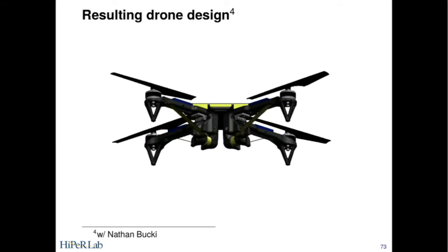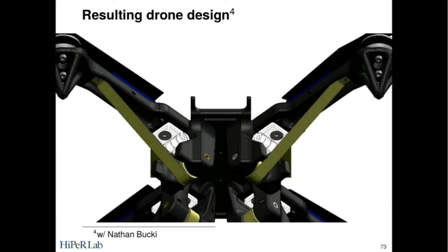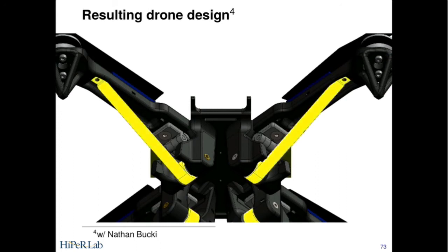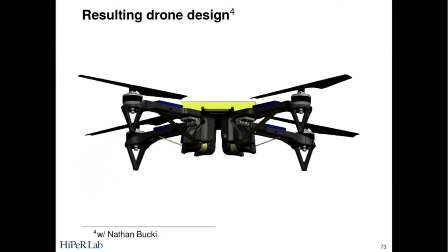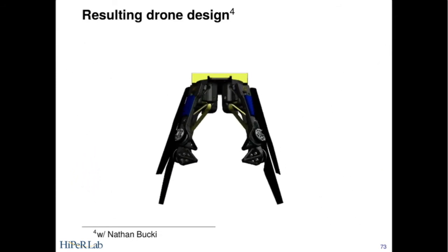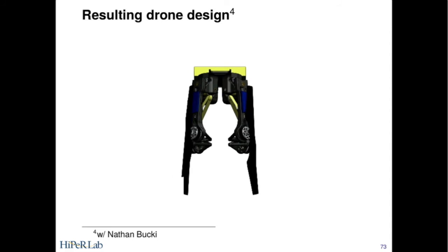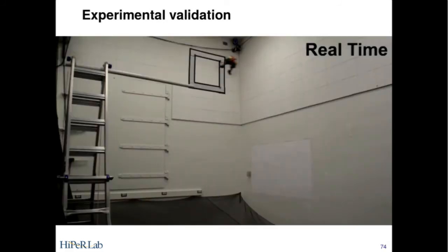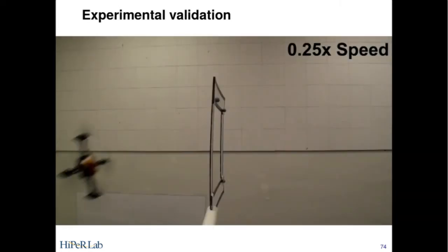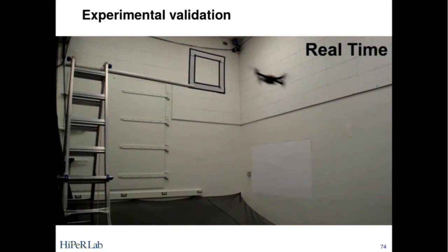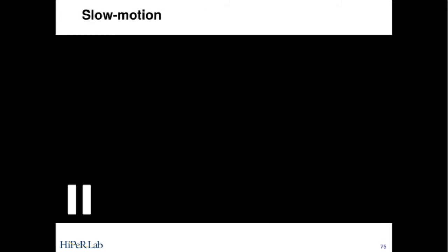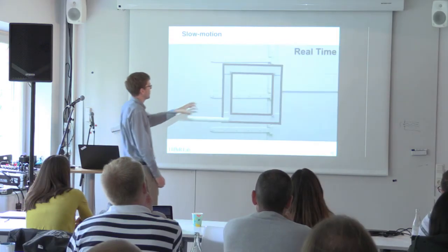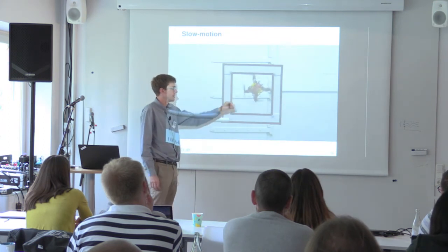And then how this actually ended up working is you have a mechanical hinge, so you have a rotational degree. Then you have these springs, with all of these components being control theoretically motivated. So where do we put them, and what stiffness, etc. And then you get something that can do something like this. Here you see the vehicle operating much like this bird, able to change its shape in real time, change from a normal quadcopter to this constricted shape, and pass through a gap that is narrower than the vehicle could possibly fit through unless it did this morphing.